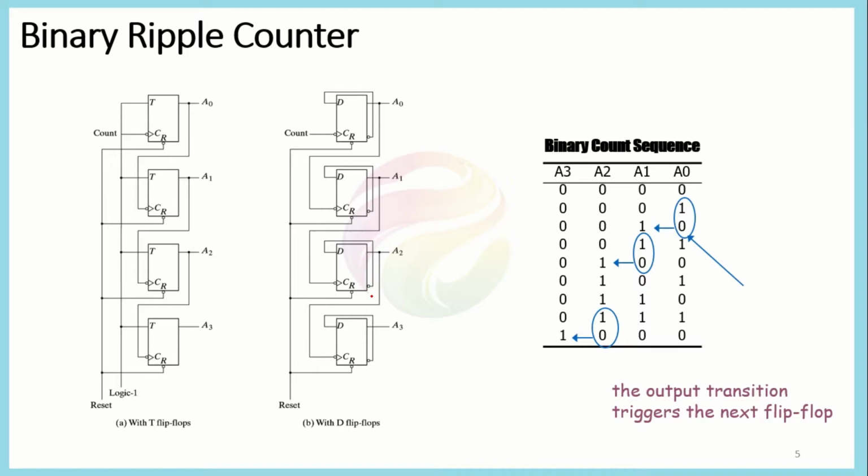This binary ripple counter could also be constructed using a D flip-flop. The configuration with the D flip-flop is presented in this way. In the D flip-flop case, the complemented output of the flip-flop is connected to the D input for each of the flip-flops. The rest of the procedures according to the clock remains the same. The system still behaves on the negative clock cycle of the pulse.